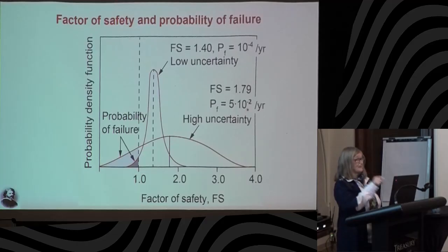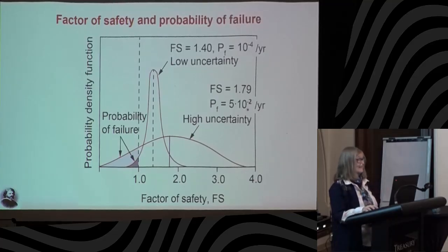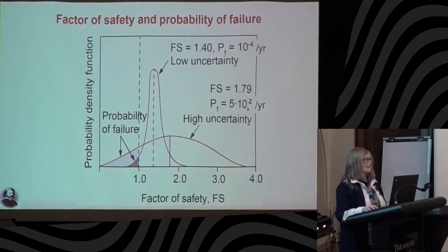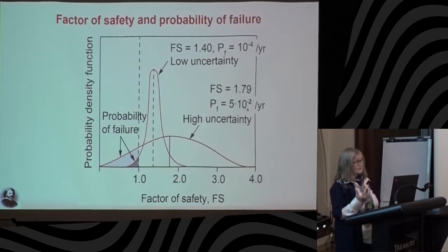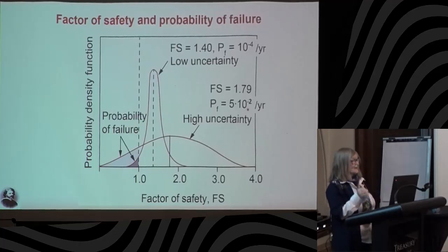And this is not something I prepared for here. It's a situation we had for an offshore platform where we had to recalculate the safety because the platform had been hit by a boat. So it just came in handy. When we saw the high probability of failure, a whole new site investigation was done. But through regulation and tradition, the same value of safety factor is applied for a slope or pile design with small uncertainties and with high uncertainties. So this is not logical.